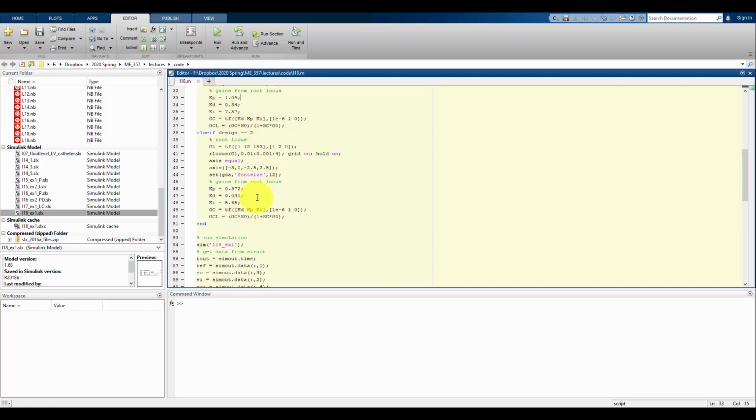We see that, again, they've shifted. We don't necessarily have any good intuition at this moment about how the behavior is going to change with these 3 different gains, or how the input is going to be different, because we see that the gain for Kp and Kd is lower than it was in design number 1, and Ki is lower, but that doesn't necessarily translate to input effort having a lower peak or a lower average or a lower total. That's why we're going to run this simulation, and see what its behavior is.